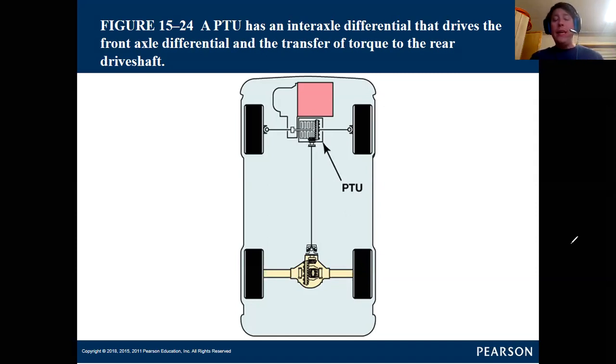They can't actually get a 50-50 split because the clutch packs in their design are not built to allow for all-time all-wheel drive. They're only allowing the rear axle to engage during a situation when it absolutely needs the rear end engaged to assist the front axle. So when I talked in the beginning about your auto button four-wheel drive units, that's kind of what they were attempting to do, this scenario.